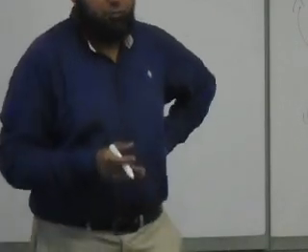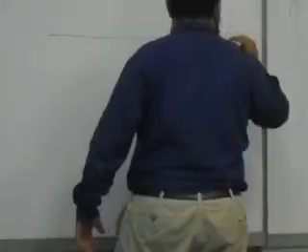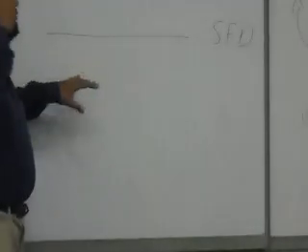So what will happen with the shear force? The relationship will be linear? No. It will be quadratic. Right? So the bending moment will be cubic. Everything is increasing in order, everything is higher in order than what was before. So for the shear force diagram now, I'm expecting a quadratic relationship. What does its shape look like? We'll talk about it.